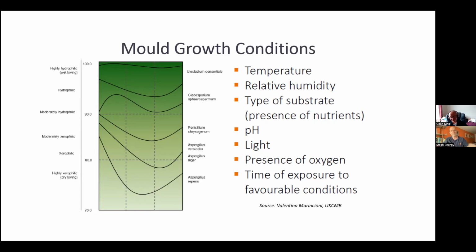If you put modern materials into an older building, it's just not a coherent strategy. This building was designed to allow water vapor to move from outside to in. In the old days, what we had was an open fire that took all the excess moisture and threw it up the chimney. We don't have those internal environments anymore. So we think that putting something that's really strong on the outside of the building will keep the water out. It won't. It will bypass that and cause issues somewhere else.